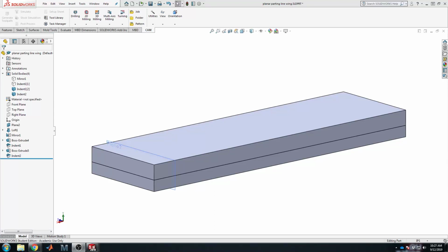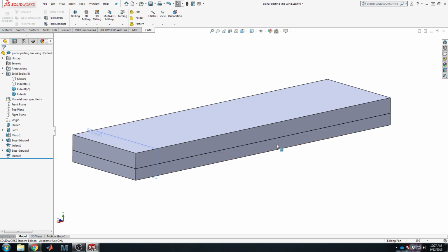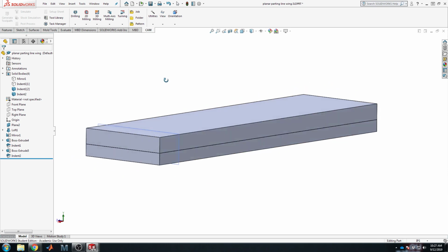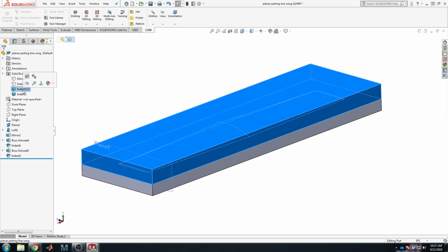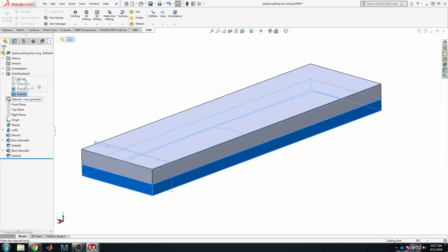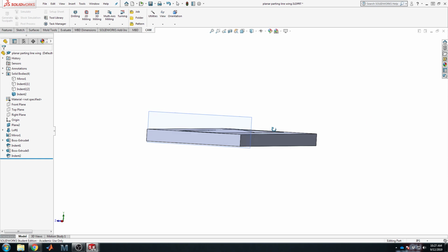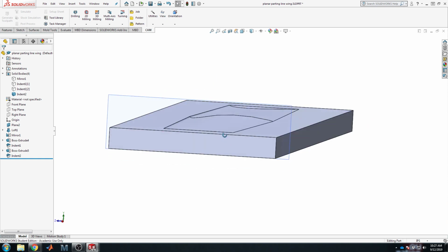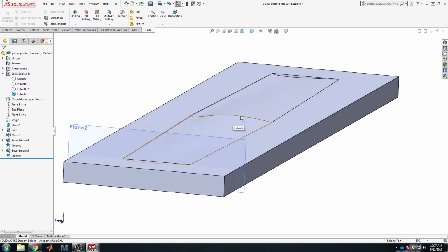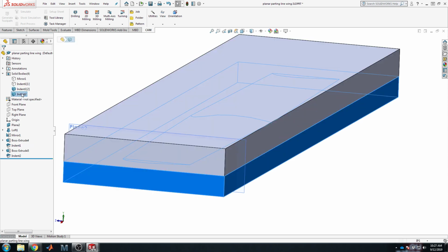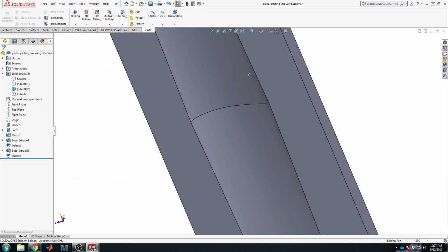This video is finally the last step of our process of getting ready to actually make a molded aircraft. So here is the simple extruded wing pair of molds. I've got them closed up so it just looks like a box, but certainly there's more work in there than that. If you remember from the previous video, this is the bottom mold of an odd wing that's Epler 423 in the middle and I think a 0006 at the tip. It doesn't make a whole lot of sense, but we're just here for the molds and not for the aerodynamics.